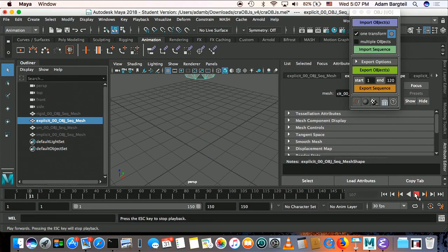Okay, so this is explicit integration. You get a nice little bounce. We're not doing elastic collision, so you don't get a very big bounce, but you do get a nice little bounce. It's nice and stable because I've chosen the time step and material properties so that happens. If I increase the time step or made it more stiff, then we would definitely see explosion like Tamar showed you earlier. So let me stop this and hide.